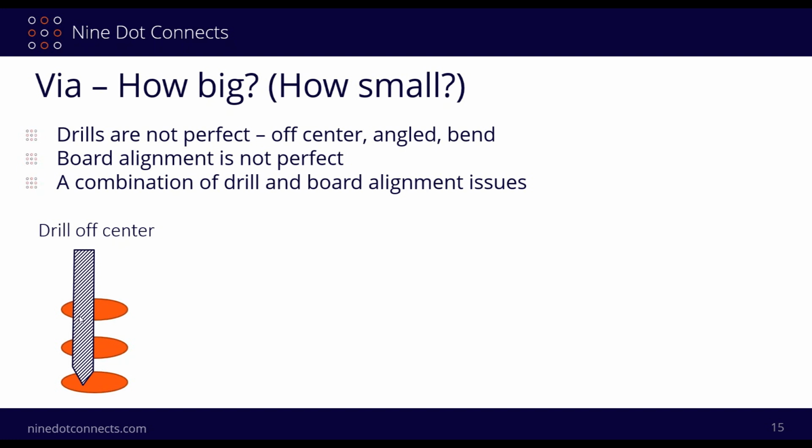If we don't have enough space or a pad or a target over here, we may do what's called a breakout, and if it has a breakout, then for certain classes of electronics, they'll actually fail it, even though it might be electrically sound. They have to fail it, especially for Class C. Another thing is that we may go in at a drill angle. If we have a really thick board, for example, a 1/4 inch board, 20 layers, we may have hit dead center over here, but if this drill is going in at an angle, it may not be hitting this thing at all by the time it makes it out the other end, or we have, again, what's called breakthrough.